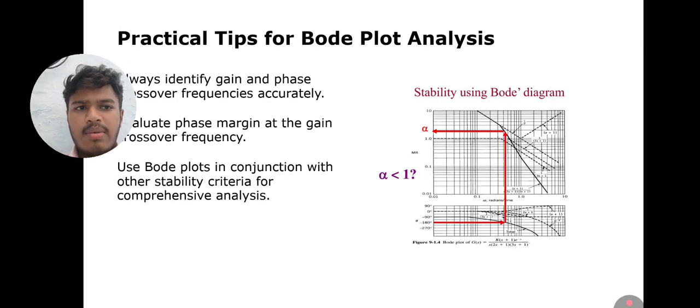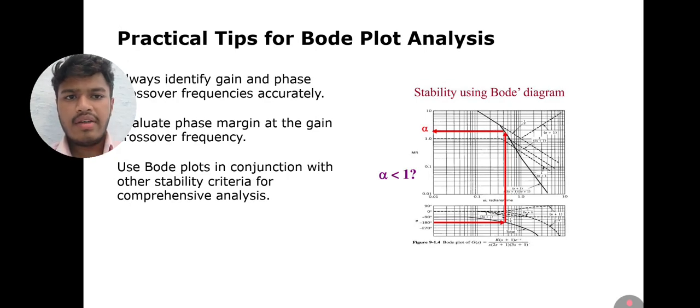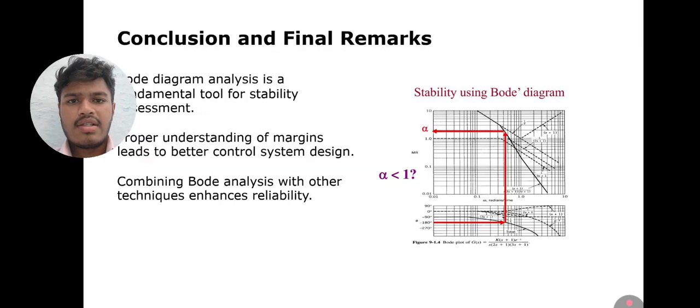Practical tips for Bode plot analysis: always identify gain and phase crossover frequencies accurately. Calculate phase margin at the gain crossover frequency. Use Bode plot in conjunction with other stability criteria for comprehensive analysis.